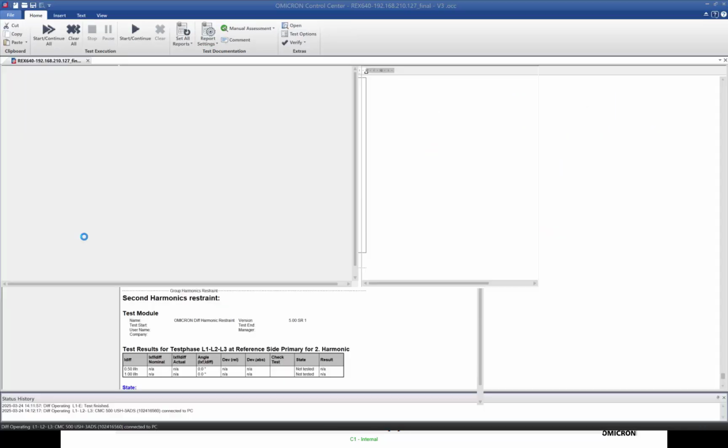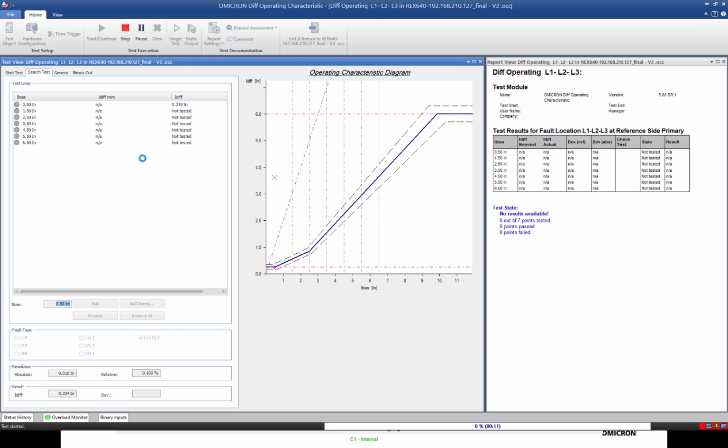There is no book or standard that tells the user to test this kind of characteristic this way, but we just give you a recommendation. So if you have two slopes, at least put one point at the beginning of the slope and one point before the end of the slope, to cover the in-between region. It is also about your time, because this test takes time.